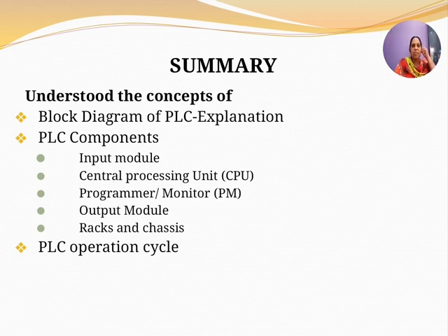Next, the CPU performs all the internal diagnosis and communication tasks. According to the program results, it writes the data into the output module so that the outputs are updated. This process continues as long as the PLC is in running mode.